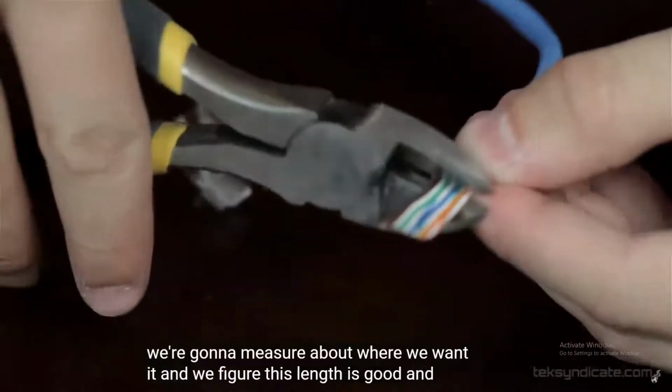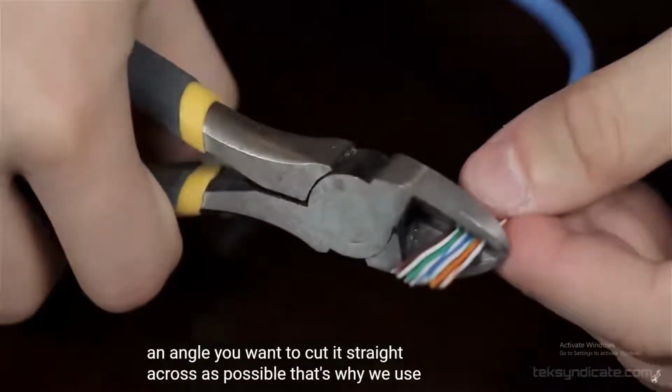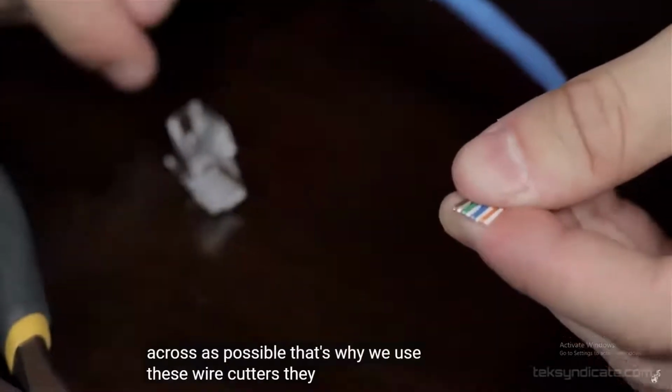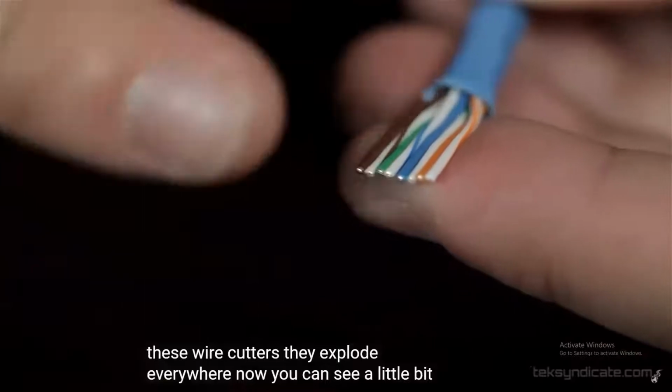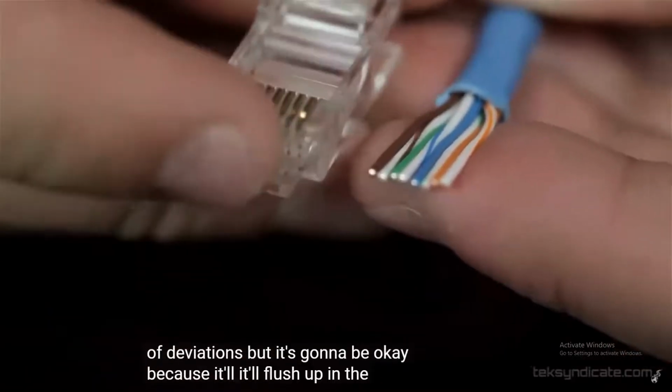And we want to cut, but we don't want to cut at an angle, we want to cut as straight across as possible. That's why we use these wire cutters. They explode everywhere. Now you can see a little bit of deviations, but it's going to be okay because it'll flush up in the end of the conductor.